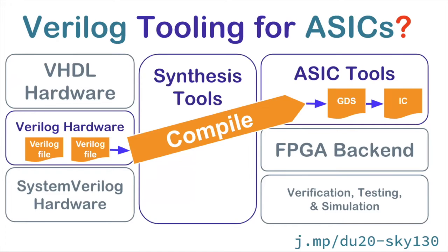Another thing is, when we implement our design using ASIC tools, in this process, EDA tools also need PDK to provide some information and some basic design cells, some basic standard cell models, SRAM and IO, and some other libraries.